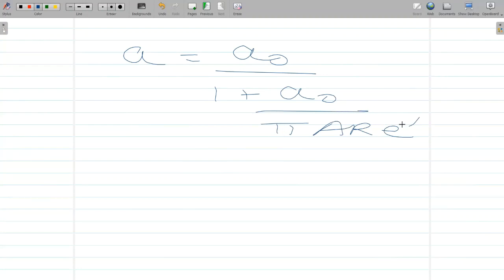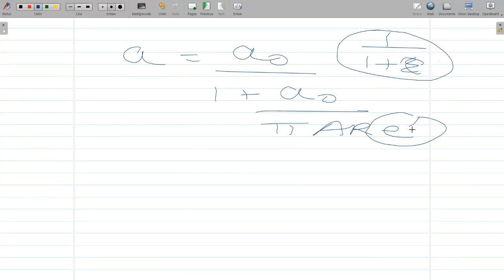Now here you need to keep in mind that this span efficiency is nothing but a truncation of the Fourier coefficients. So if you truncate the Fourier coefficients, that's how you get your efficiency factor over here. Let's not go into too much detail on the efficiency factor, and let's just do this problem, and preferably let's keep everything in radians.